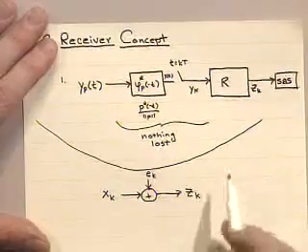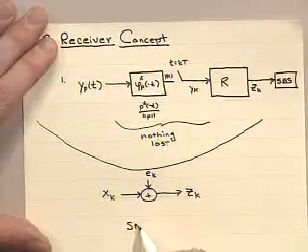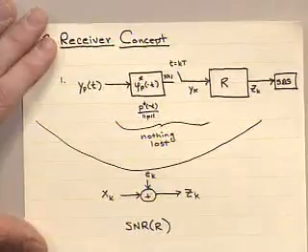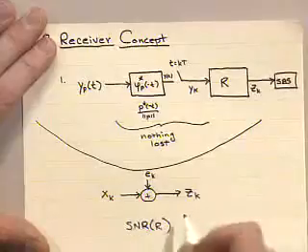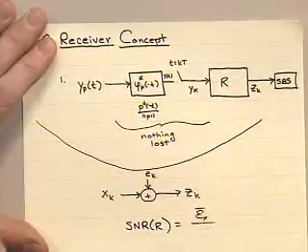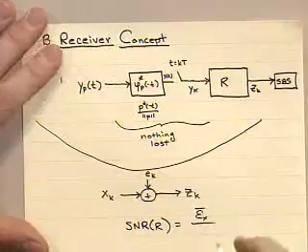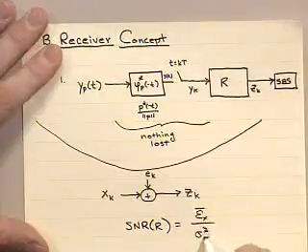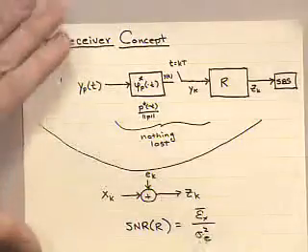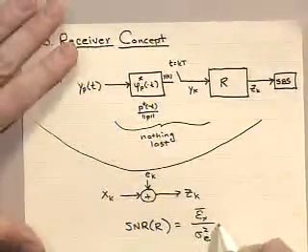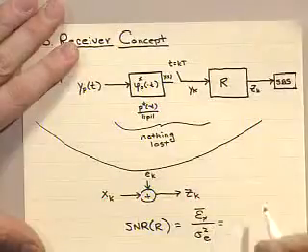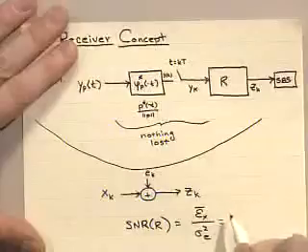And so I will have then a signal-to-noise ratio, which I'll call the signal-to-noise ratio for any given receiver R, which is going to be Ex bar, the energy of the symbol part that made it through, divided by sigma E squared. And if this is a complex system, then if I find the variance as a complex number, I'll need to divide by 2 to make this energy per dimension on top and bottom.